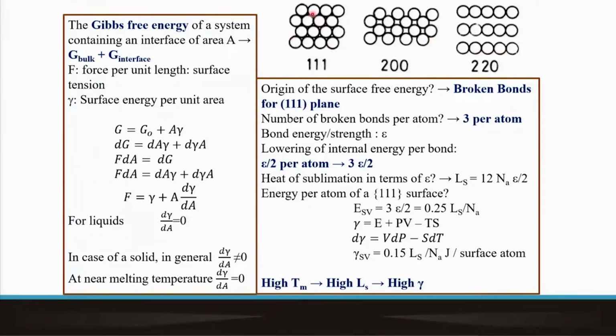then what we realize is that the crystal, depending on the section we have chosen or the crystallographic plane of reference we are discussing, will have different types of geometry or configuration of atoms, the way they pack themselves. For example, here we can easily see that 111 is the crystallographic plane. Assuming this is an FCC crystal, it will have the largest packing, and as a result any atom with identical surroundings is surrounded by 6 neighbors, so the one in the center enjoys 6 bonds.